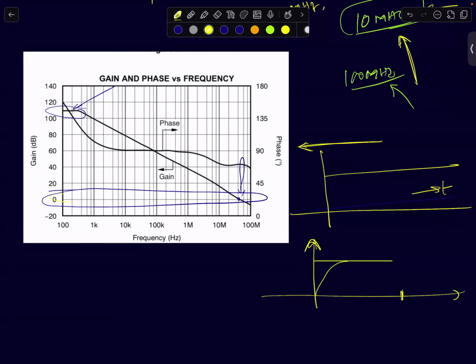So with your weighing machine, initially you stand, it stabilizes and reaches a stable value. Then this voltage signal is converted to a digital signal and all that. Okay, so that's how your weighing machine displays your output. For a weighing machine, because your input signal is DC, what matters is your DC gain. So your DC gain should be very high. If I want very precise amplification of this signal, then I need a very high DC gain. Okay, so this is something for you to keep in mind.